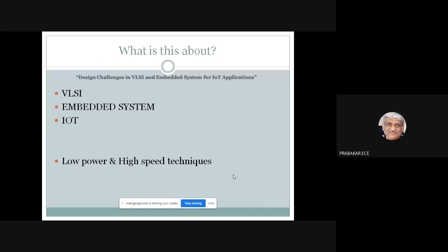No issues. But in the case of a microcontroller that is brought inside an FPGA, in the Altera brand they call it Nios, and Xilinx also has some PowerPC processor or something like that. Supposing in a microcontroller I don't want a DMA controller, I can remove it from the hardware itself, so that the area will be reduced, the static power will be reduced, and the dynamic power will be reduced because of unwanted transitions. So I can have reduced power consumption.